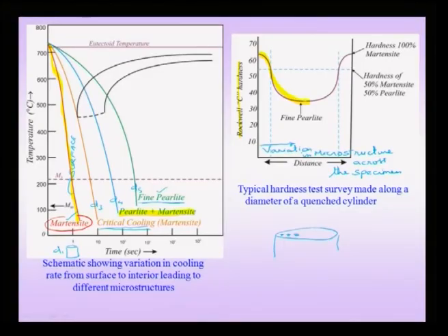Now, this is one of the motivations, as we shall see later, to produce what we call alloy steels, so that my CCT diagrams are moved towards the right. That means, in alloy steels you will note that the nose of the TTT diagram, which is typically, as we have noted, of the order of just a second. That means the quenching rates you need to employ are very, very large. But suppose you are able to move the nose of the TTT diagram to the right, that means that I can apply less severe quenching rates to produce martensite.